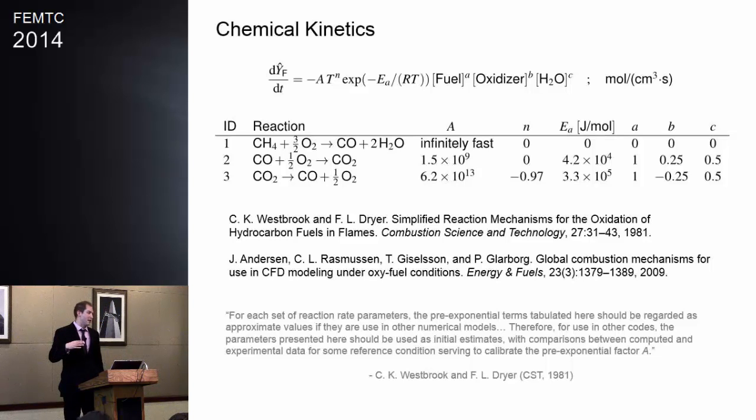And so that's why we wrote that integrator, so that we can efficiently handle that reaction. But the other thing is we wanted to look more in depth at how we predict CO. So this goes into what I was talking about earlier: we want to predict CO for under-ventilated fires. And so here are 3 reactions that we've been using as far as our CO predictions are concerned.